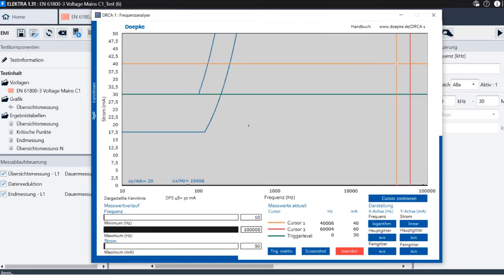If we are scaling down to a certain amount of milliamp, you would be able, if we switch on the motor, which we are going to do soon, to see different leakage currents. What you also see here is that for the lower frequencies, for 50 Hertz for example, the leakage current is not too high, but for the switching frequency of 8 kilohertz, it's pretty high. And this is clear because we didn't add any filter so far, which adds leakage current to the lower frequency as well.